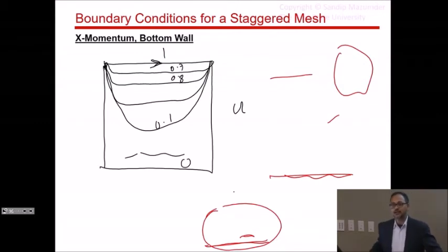Why do you think you'll get that? So first of all, will these contours be symmetric between left and right boundaries? Yes, no. How many say yes? So majority say no. So why will there be asymmetry? Pressure is 0, first iteration. Uniform everywhere, no pressure source.